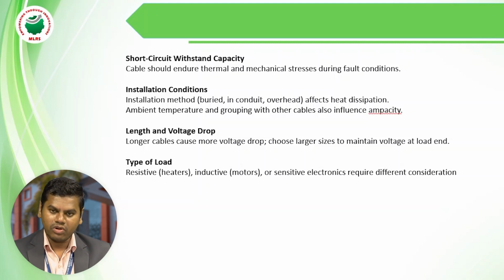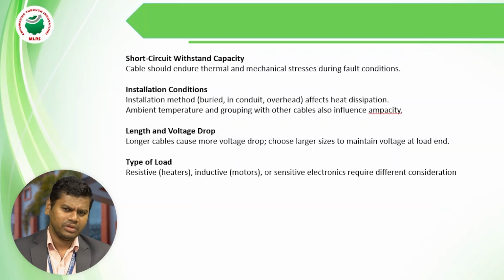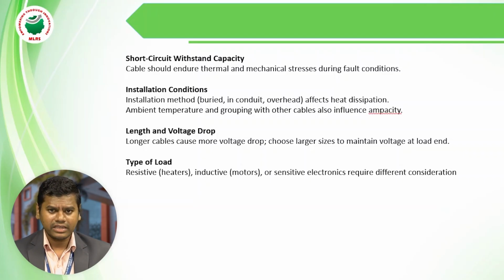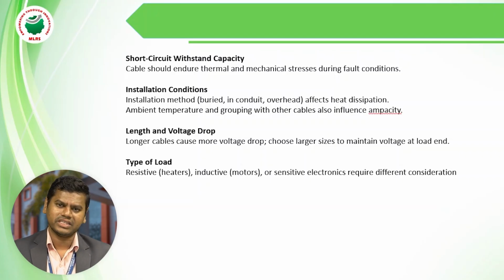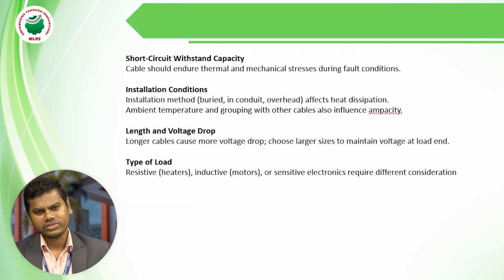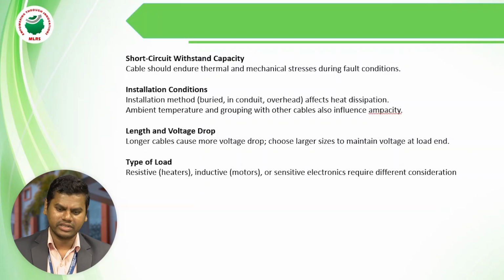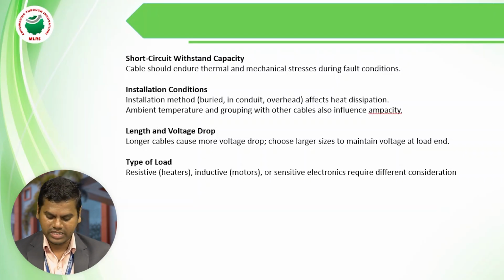Length and voltage drop. Longer cables cause more voltage drop. Choose larger sizes to maintain voltage at the load end. Type of the loads: let us assume three loads. What are the three loads? Resistive load, capacitive load, inductive loads. Resistive loads are things like heaters. Inductive loads are things like motors. Sensitive electronics require different consideration.